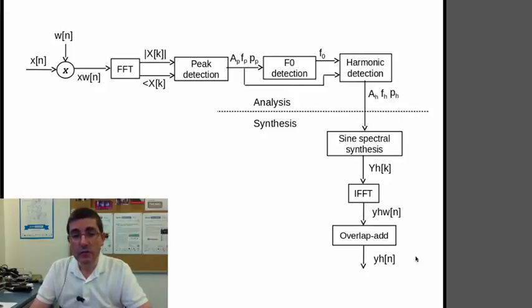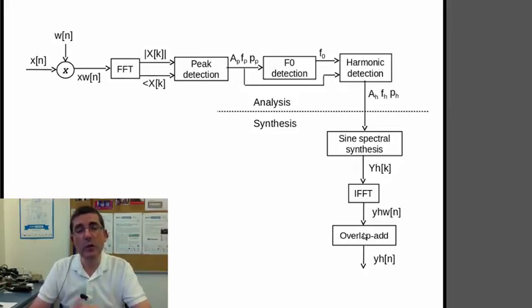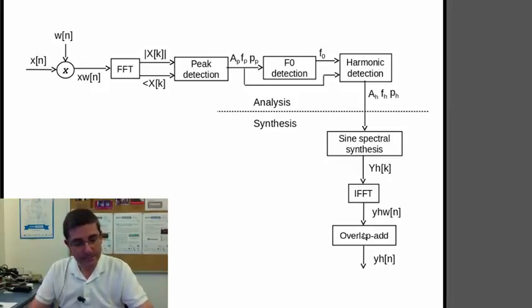And then this goes to the synthesis, and the synthesis is exactly the same as in the sinusoidal model. So we generate the sinusoids in the spectral domain, we do the inverse FFT, and then we do the overlap-add to reproduce the whole sound.